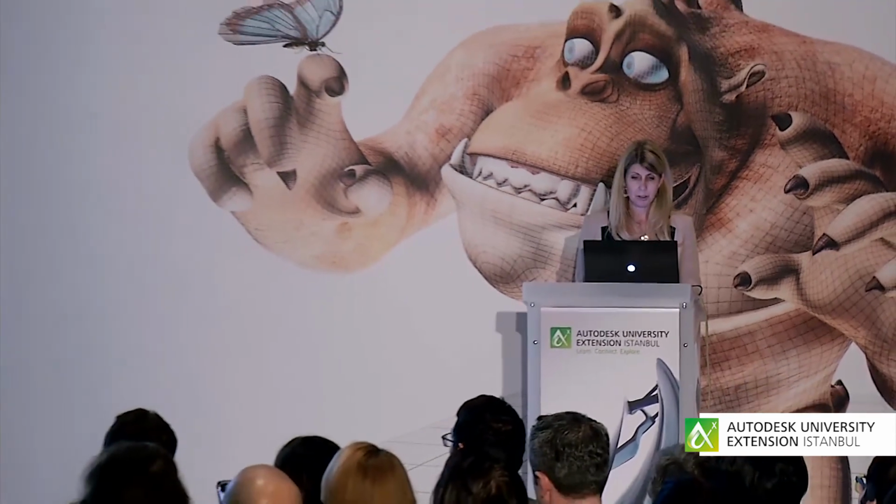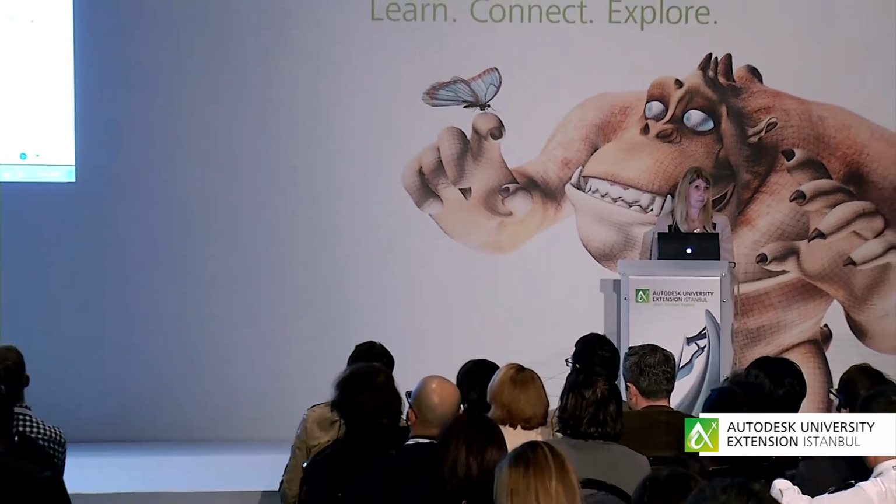So let's go over to tips. This drawing right here. There's some fun things in here. How do you get more than one hot grip? Hold down the shift key, right? You can have multiple hot grips holding down the shift key, and then you could stretch them any way you wanted to all at one time. Shift key.